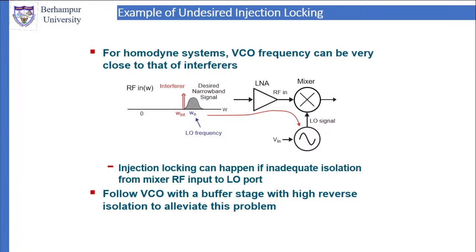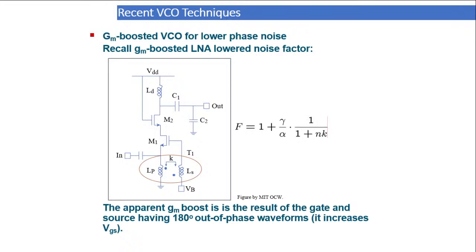Follow the VCO with a buffer stage, in this case with high reverse isolation, to alleviate or avoid this problem. Follow the VCO with a buffer stage.